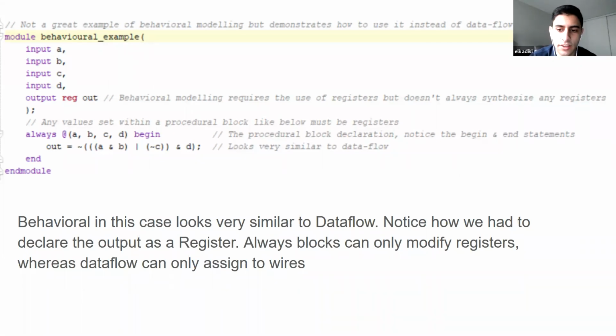Yeah, good question. So using the asterisk is fine. You can typically use that, and it'll just tell Vivado to put whatever is actually sensitive into the sensitivity list. It'll just leave it to Vivado to make the decision. Typically, you can do it, and it doesn't create latches. It works very well, but I don't know if using it is good or not. I know that older versions of Vivado and ISE will not support it because that's a new thing they've added. You can use an asterisk though. It works the same way.